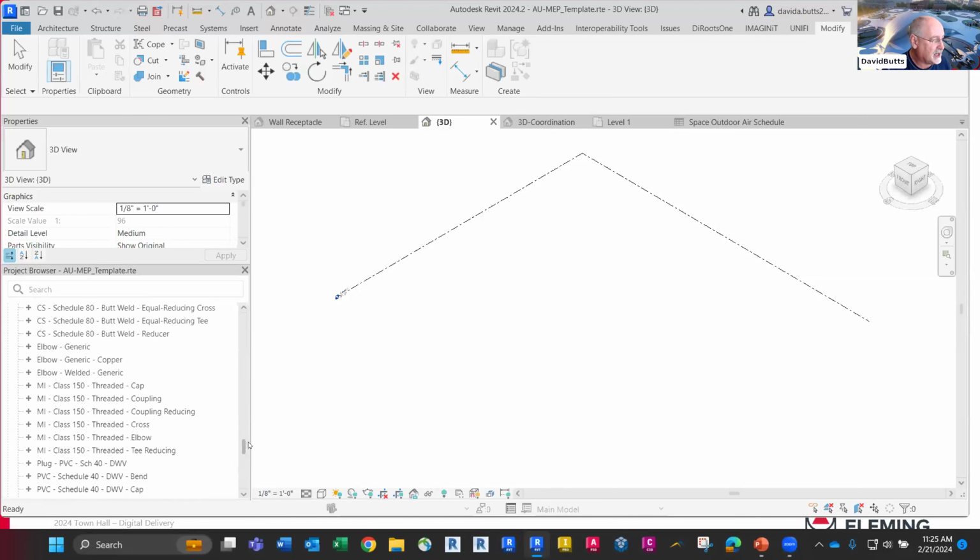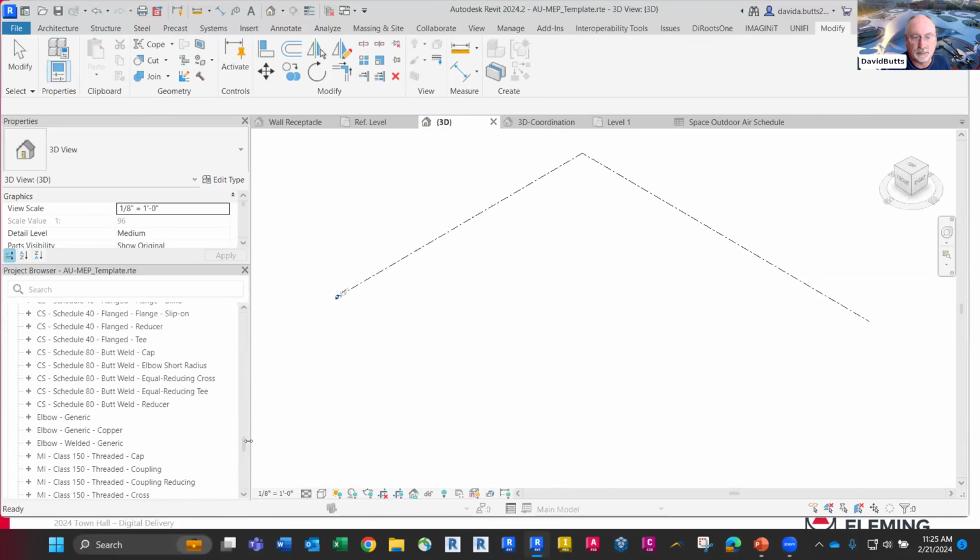And then when I get to my pipe families, I'm actually using pipe families that are the most common ones that I use. I'll make those pipe types and put those in there so that they're pre-baked, so somebody doesn't have to go and load them up from a library. The whole point in what you're doing with your template is you have to go back and look at what's important and what you need to use in a project and make sure that you got it in there.